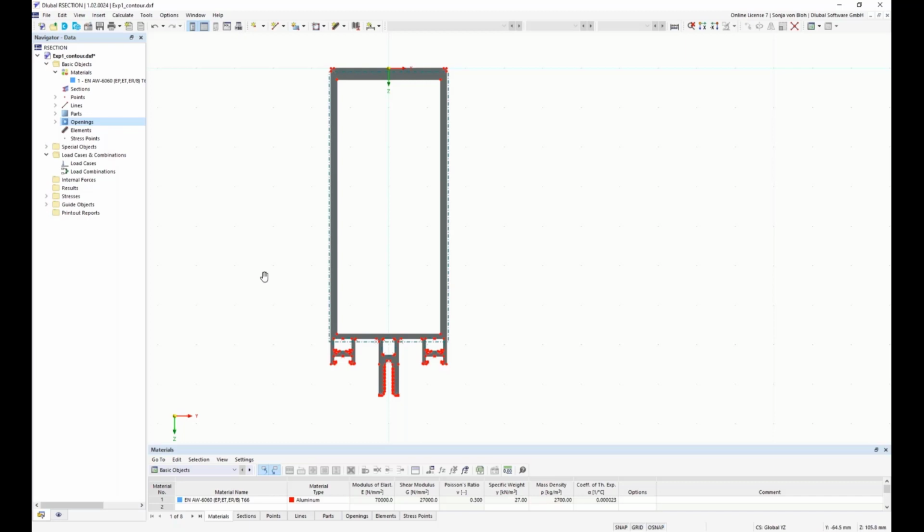The subpanels are automatically generated based on the standard selected in the base data dialog. These cannot be changed. If no elements are defined, a cross-section classification in RSECTION and the design models of RFEM or RSTAB is not possible. And it's also not possible to calculate the effective cross-section. In the design add-ons of RFEM or RSTAB, this cross-section is then designed according to the cross-section class 3.